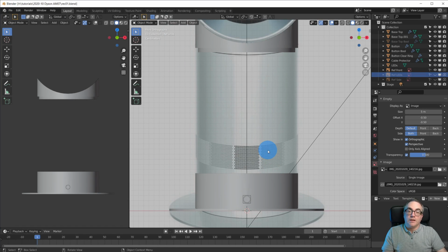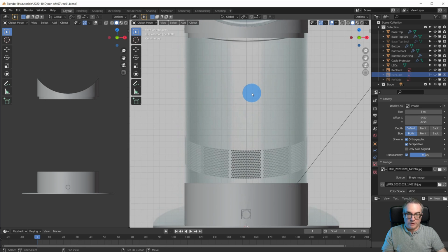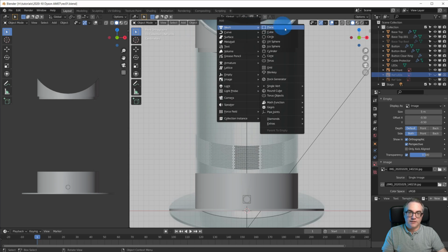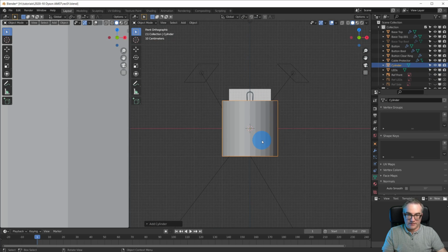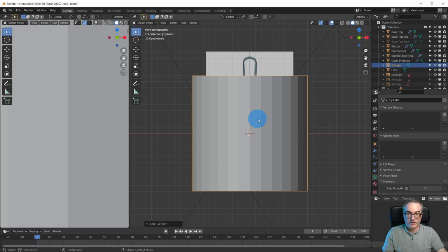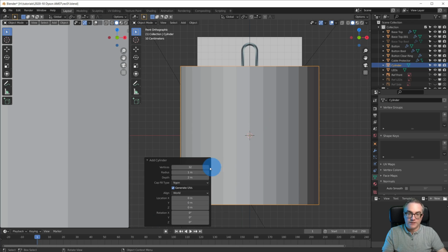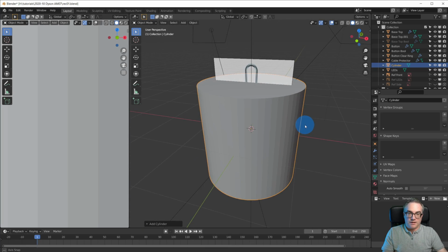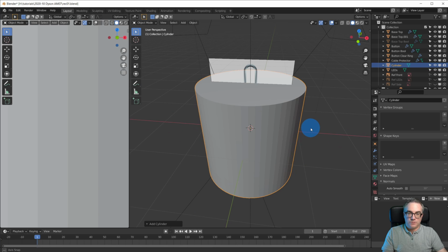And now I'm gonna take a cylinder and place those holes on there. So now this is really, like I said before, the only part where I'm going to add a real cylinder. The cool thing about adding a real cylinder in Blender is that it comes by default with a very nice UV map. Now I do want a little bit more detail, so 64 I think.